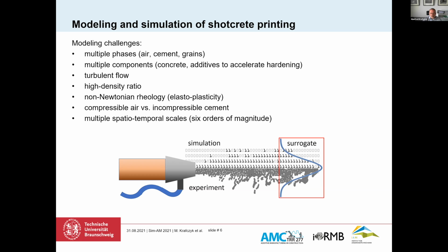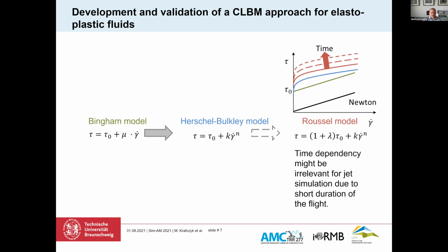And what we're trying to do is to come up with a suitable model for this jet. And so I'll just report on the first steps because this is ongoing work. So first you have to tackle this feature of non-Newtonian rheology. So you can start with Bingham model, go to more complex Herschel-Bulkley model.